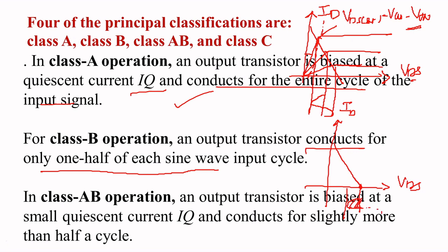The other half of the signal will be clipped out. So basically you want to modify the circuit to get your full swing. With one device in class B you will be getting one positive swing. Similarly, you want to add another complementary device on the downside to get the other part of the signal. That we will discuss in the coming slides.